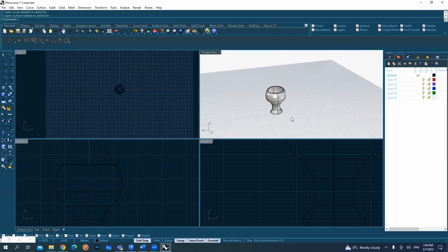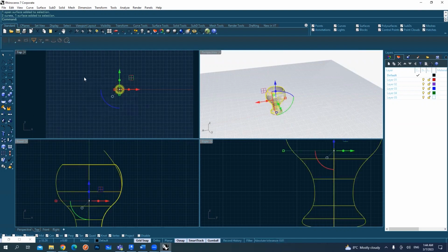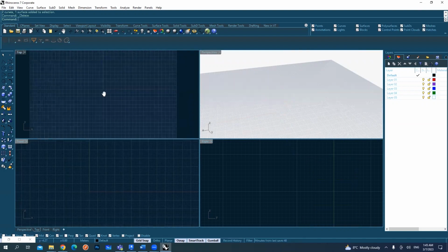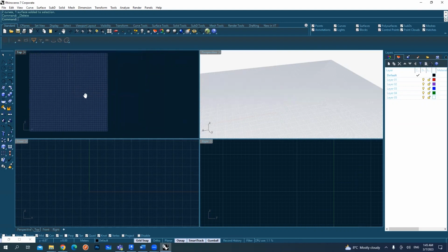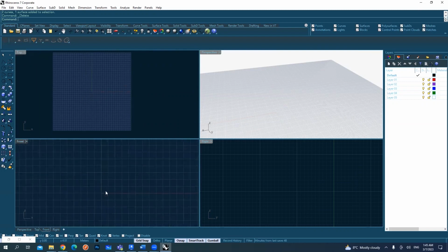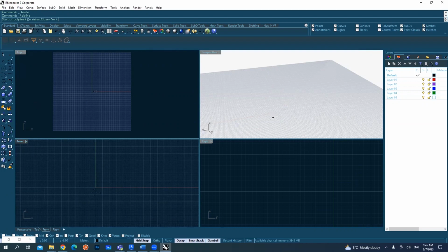So you have a kind of a profile and you want it to walk all around the room, for example. So this is what we will do with the sweep now. I'm deleting my loft. For the sweep, I want one profile to be on the XY plane. So it's a different plane, and the profile would be on the side plane. Let me just start with that.